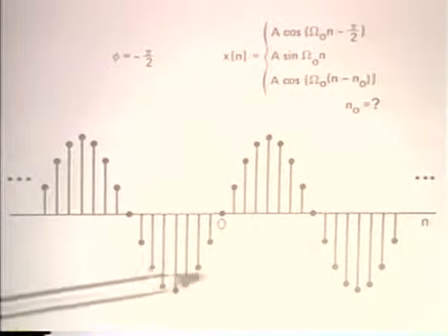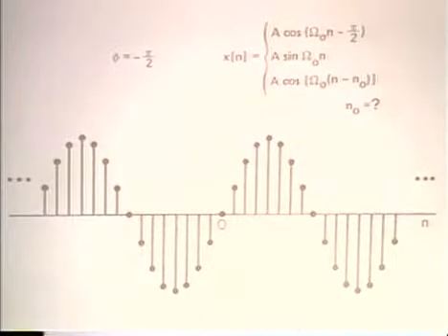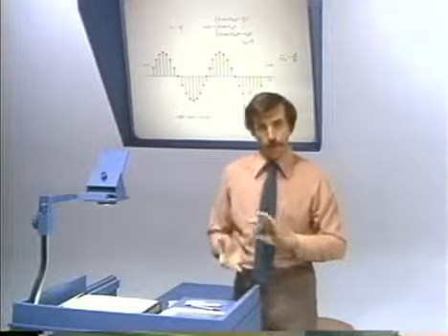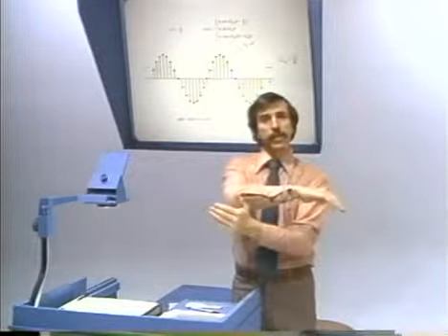Now, looking at this sequence, which is the sinusoidal sequence, the phase of minus pi over 2, that has a certain symmetry. And in fact, what we see is that it has an odd symmetry, just as in the continuous time case. Namely, if we take that sequence, flip it about the axis, and flip it over in sign, then we get the same sequence back again. Whereas with zero phase, corresponding to the cosine that I showed previously, that has an even symmetry.